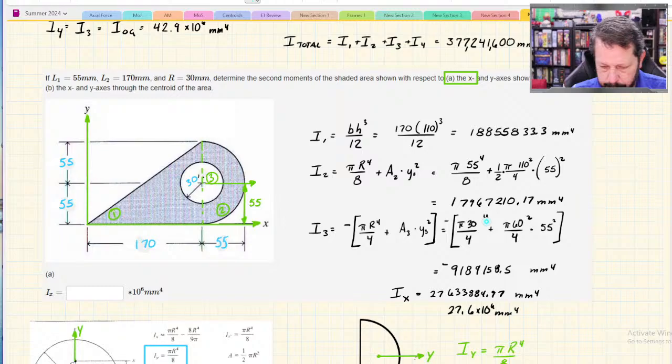All right, SolidWorks doesn't allow me to move free. I know. Yes, that's okay. So you don't have to tumble. You know, that's called tumbling. You can do everything from the front view. Even for your simulation, you can do everything from the front view, because at least Lab 1 is a flat part. So you just draw the shape, the cross section, and then extrude it into the screen, and you don't even have to rotate.